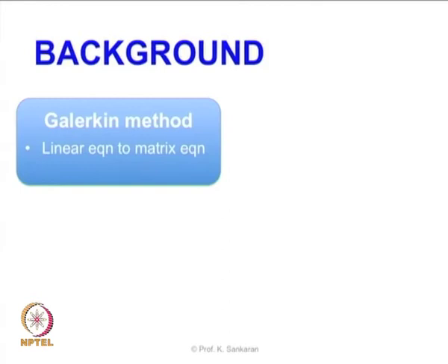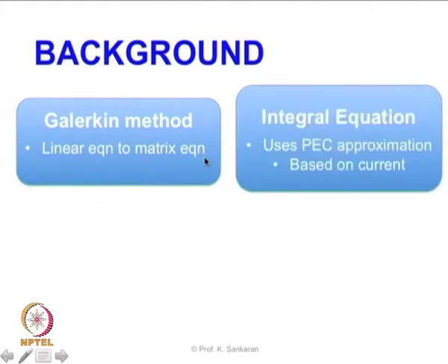That being said, there is a similarity to the Galerkin method or the finite element approach which we discussed. In the Galerkin method we are basically going from a linear partial differential equation to a matrix equation. In the case of the method of moments, we are going to start with the integral equation, not the partial differential equation like in the case of the Galerkin method. We are going to use a PEC approximation, the perfect electric conductor approximation, on the boundary conditions, and the entire approach is based on currents.